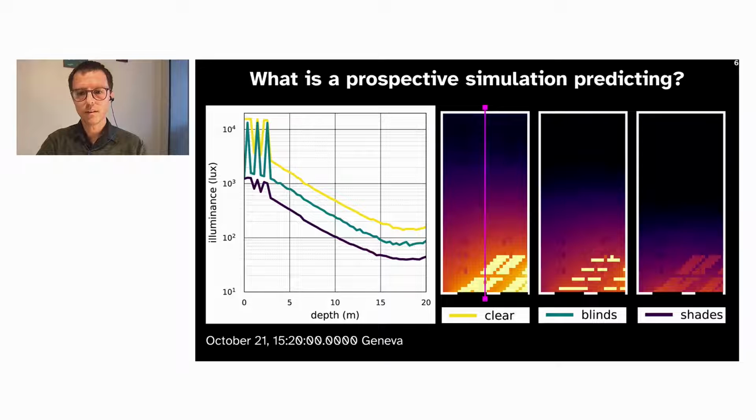Knowing the transmission properties of these facades, we can even be fairly confident that the relative difference at a single point between these options will remain fairly constant across almost any sky condition. But what happens if the room shapes are different, or the windows are different sizes, or on different orientations, or we assume the blinds and shades are dynamic, or if we assume there are different control algorithms for the shades and blinds? In these cases, we cannot generalize from one time step to all the others, or from one point, or even from one section. Only by fully characterizing the spatial and temporal domain can we hope to understand the trade-offs between interventions.